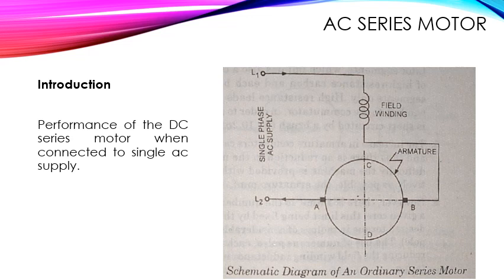So in case of AC operation, in addition to rotational EMF and reluctance voltage, transformer EMF is also developed, which will be maximum for conductors A and B, indicated in the figure on the brushes. So that's conductors lying midway between the pole centers, because the armature coil with the greatest EMF is the one whose magnetic axis is parallel to the main field, and consequently at the commutator the voltages developed by transformer action are greatest between segments just where the brushes are situated at the so-called neutral points.